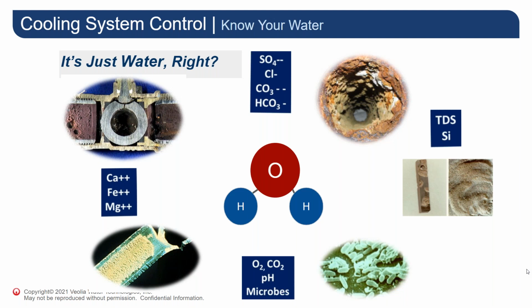And lastly, we can't underestimate the presence of microbes or an environment that's conducive to microbial growth, because that can become both a corrosive and a fouling nightmare that can plague your system and its operation and create nightmares for your operators all year long. Don't forget, cooling water is wet, warm, and due to the operation of the tower, typically a fluid that is loaded with organic nutrients, which foster microbial growth.